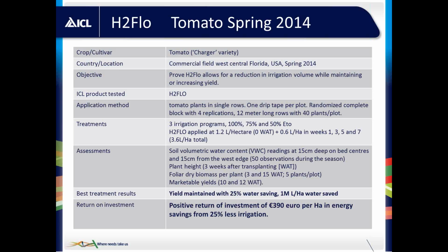So our best result here was that we managed to maintain the yield, so the yield was the same as with the 100% irrigation, with a 25% water saving. And this was actually equivalent with this crop to over 1 million litres per hectare of water saved. So there was a positive return on investment of almost 400 euros per hectare, just based on the energy, the pumping savings from using 25% less irrigation.